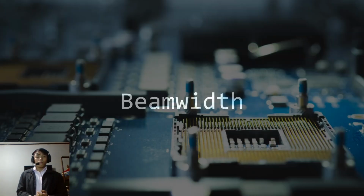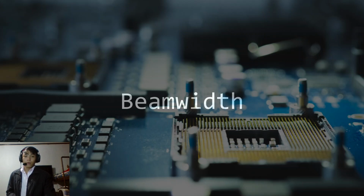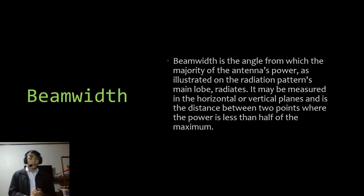So, beam width. What is beam width? Beam width is the angle from which the majority of the antenna's power, as illustrated on the radiation pattern's main lobe, radiates. It may be measured in the horizontal or vertical planes and is the distance between two points where the power is less than half of the maximum.